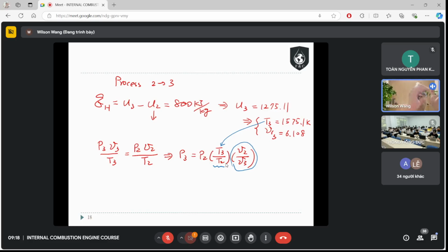So that is why in a lot of combustion experiments, when we are trying to study, for example, the heat release rate, ignition temperature, or ignition delay, some combustion experimental studies, we always consider that volume is constant.